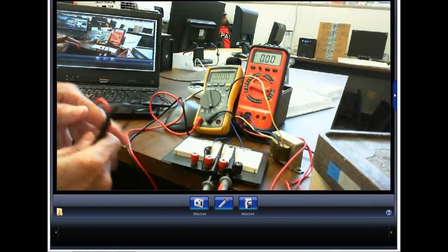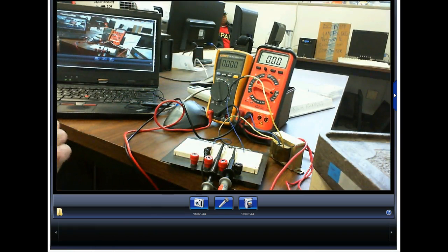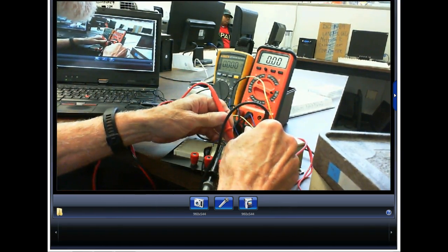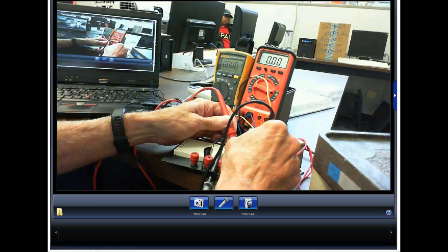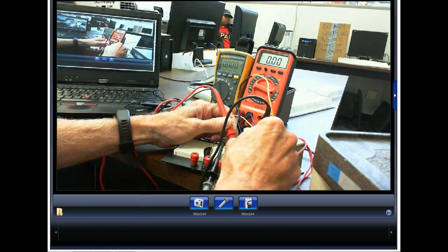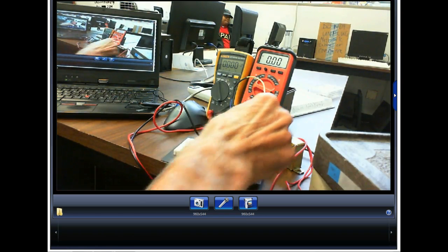So what did we calculate? So let's put it back on the meter. Y'all see Scott's meter? We calculated 2 point something milliamps. And so we got 2.1. Now why is it probably low? Well, it's probably low because it's not exactly a 2.2 k ohm resistor, right? So we measured 2. So that looks real good, guys.